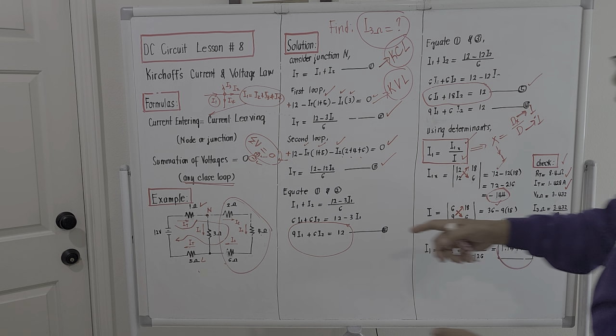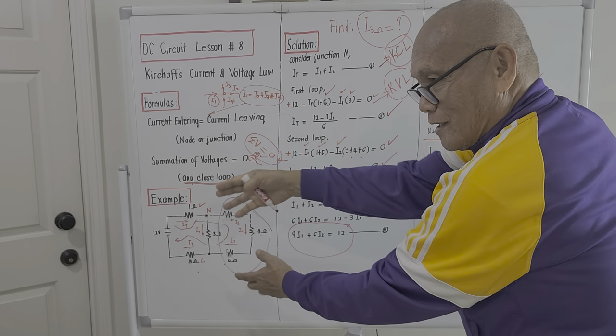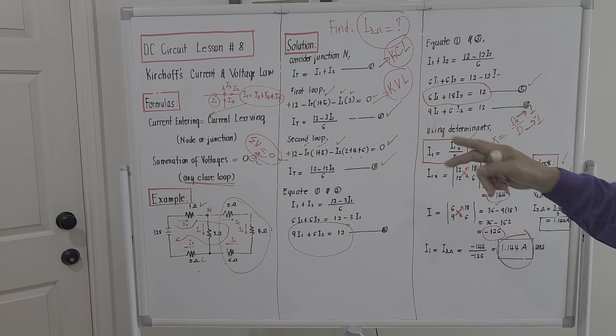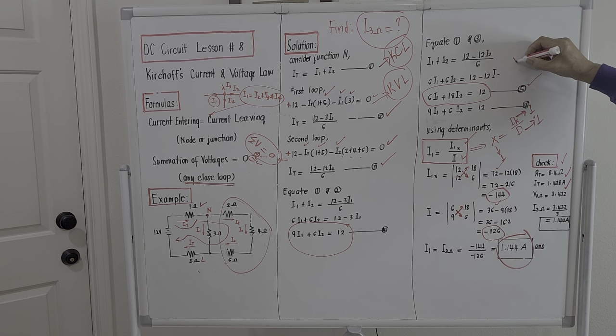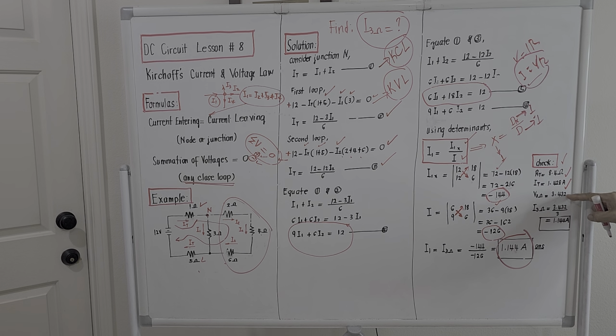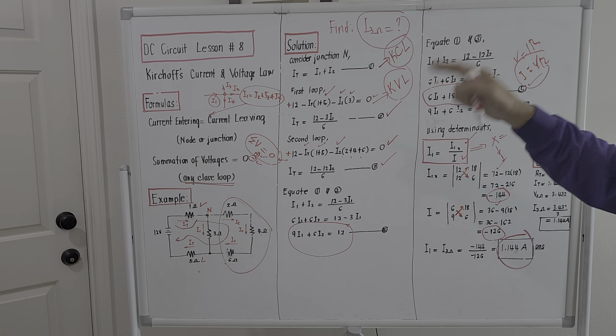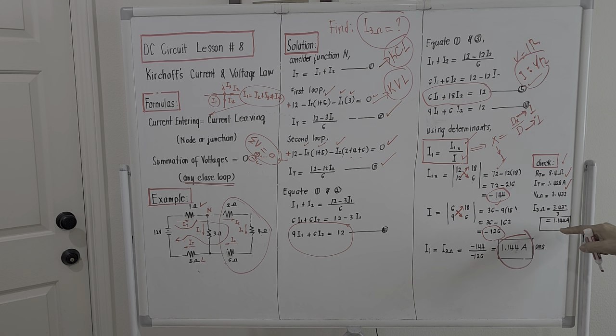Okay, we know already the voltage over here. By using the total resistance method, we are just checking our answer. If we try to compute for the current, voltage is equal to IR, so current will be equal to voltage over R. It will be 3.432 over 3. The total current passing through the 3 ohm load, as you check against the Kirchhoff's current and voltage law solution, what comes out is 1.144 amperes. That is by using the so-called total resistance method.